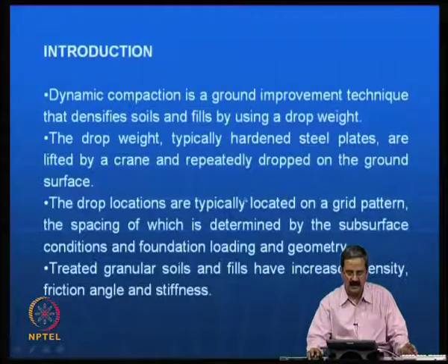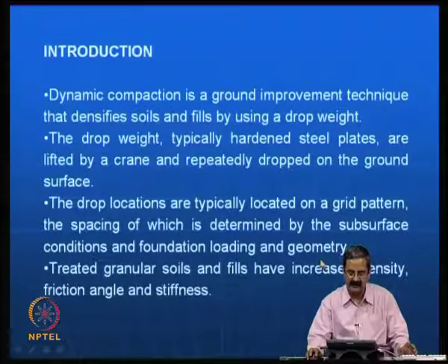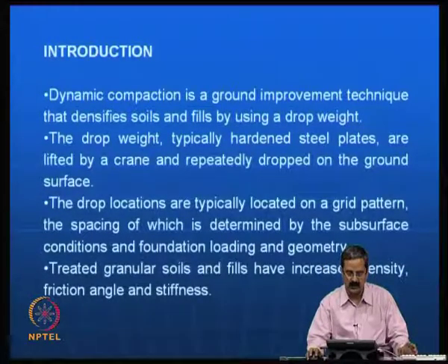The drop locations are typically located on a grid pattern, like we will see in a design in a few minutes, the spacing of which is determined by the subsurface conditions and foundation loading and geometry. Most of the time we have a grid pattern, and the main thing is the subsoil conditions, to what extent the soil needs to be improved, what foundation loading is coming, and the geometry. All that is very important.